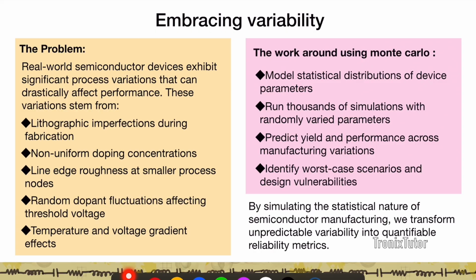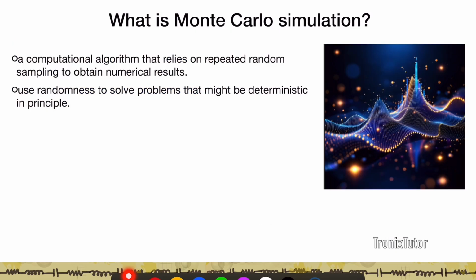When you start off a process in the fab, you might start off with a pretty loose statistical model, and as you build the process and learn more about the variations that can happen, you can build a model which closely resembles the actual manufacturing process.